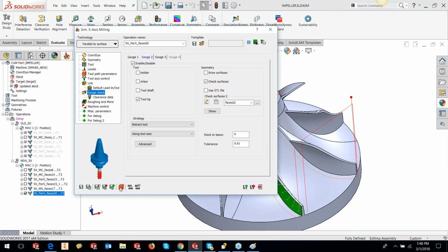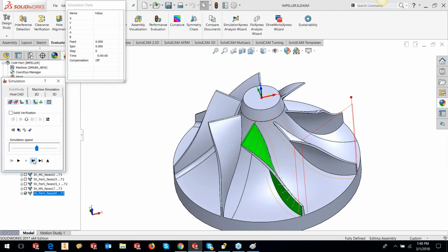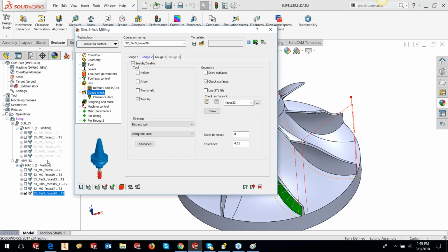Okay, so what I have here is I just get two nice passes, which look something like this. I'm making sure that I don't get any collisions on the side. I don't have any collisions with the bottom, and it has cleared the blades nicely. So I just get one pass on either side. And once I have this pass, which basically tells me that I have an area, because I've got two blades, it's machined both the blades and now understands the area between these two blades.